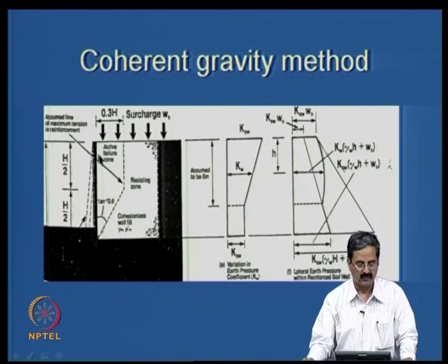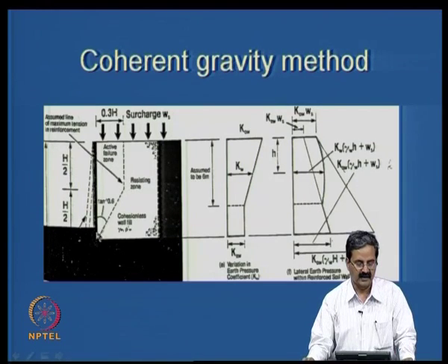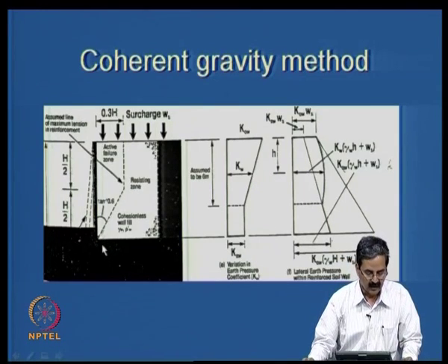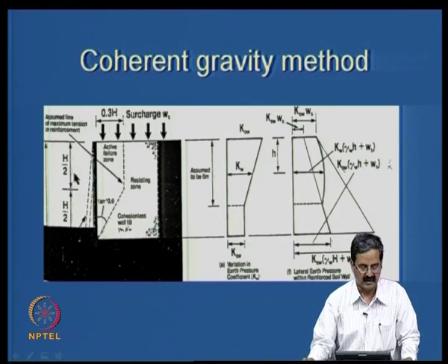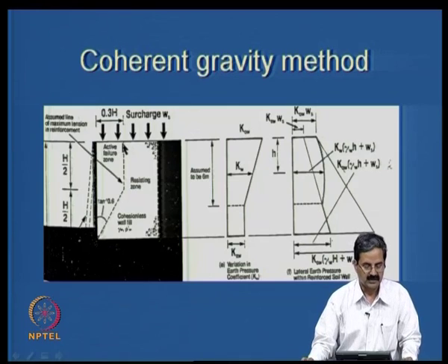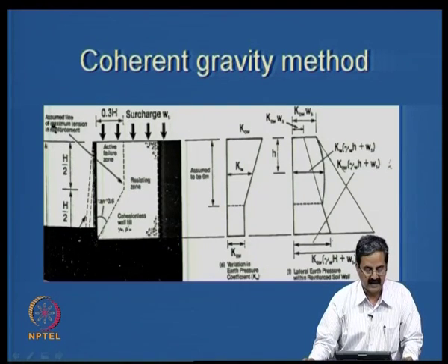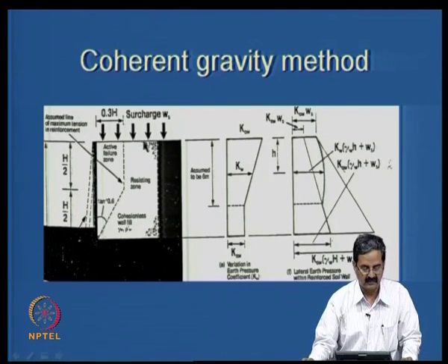Similar to that, we have the location of strains here, right? So you construct this particular line, and based on their observations, for a distance of H by 2, it is about tan inverse 0.6, and for another H by 2 in height, it will be a straight line, and this particular distance is 0.3 H. So this is the line of maximum tension in the reinforcement.